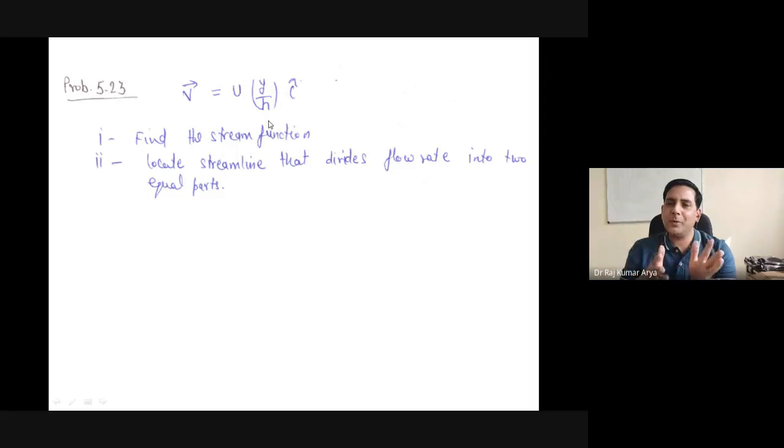Have you solved any problem where you have derived the velocity expression? Yes, sir. Yes, momentum balance. You did a momentum balance for the rectilinear coordinate also. We were talking in the last class over a flat plate. There you got a parabolic profile. So ideally it comes parabolic, but sometimes people, for ease of calculation, say linear profile also. So it comes only from there.